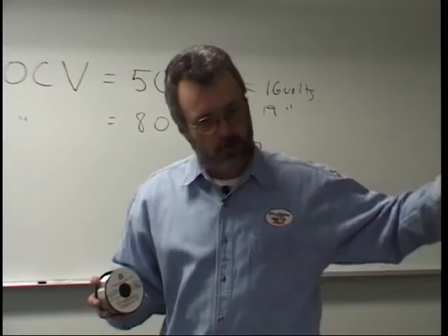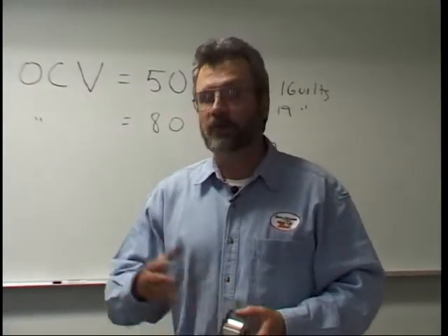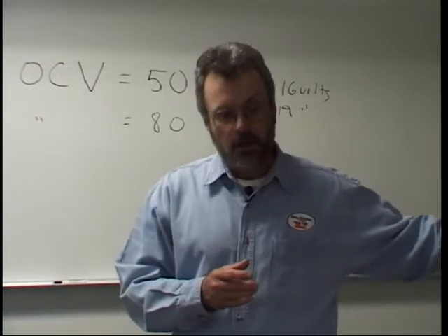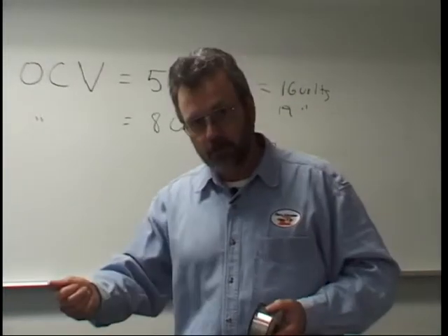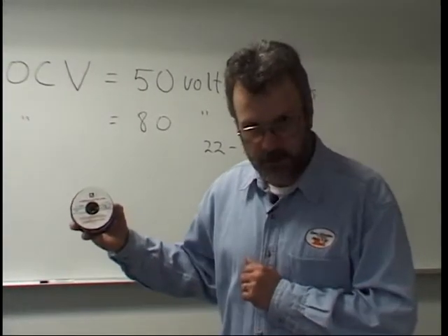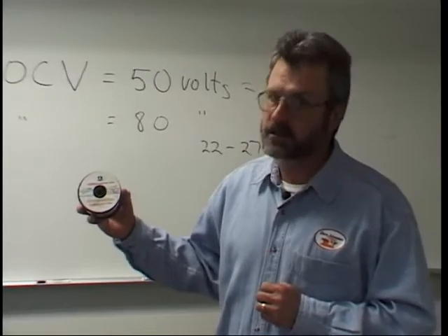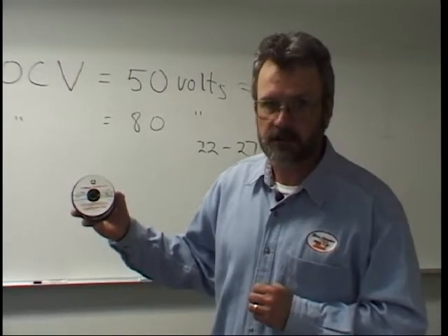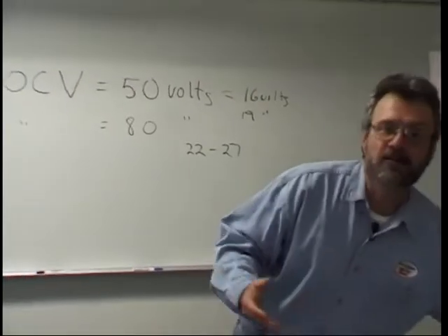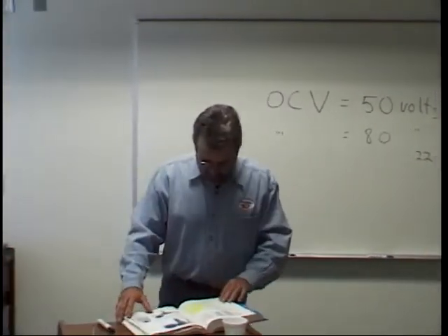We have a wire feeder that pushes the wire all the way through and it comes out of your gun, which you're using. We have a pull gun, which will be pushed at the wire feeder and pulled at the gun. And then we have these self-sustained spool guns. So three different types of guns. So pay attention to that, because you're going to get some questions about these different types of wire feeders and guns. And we haven't even gotten to Flux-Cored guns yet, so we'll get to those in a minute.